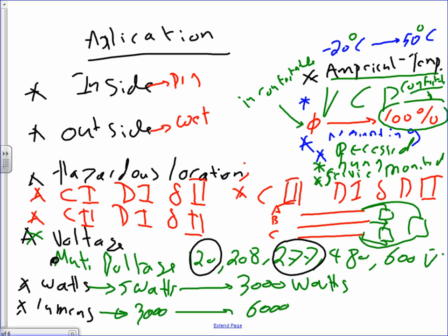480 becomes, guys, parking lots and bigger lights. They can burn them at 480. Anybody know the advantage of burning lights at a higher voltage? Lower current, which means cheaper operation, less losses, which means lower voltage drop.